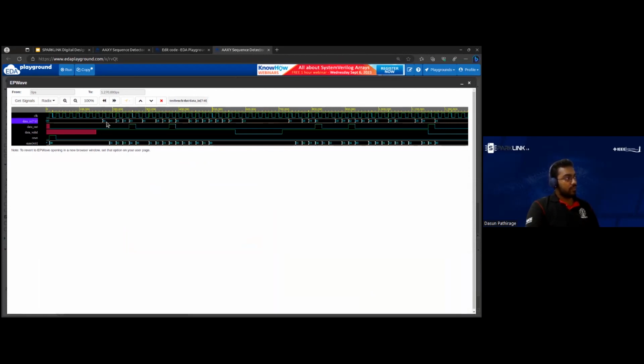But you see only 141. What is the reason? Okay, I zoom it in. So you can see there are two clock cycles here. First 41, then again you receive 41. That means two As are here because you have two clock cycles.